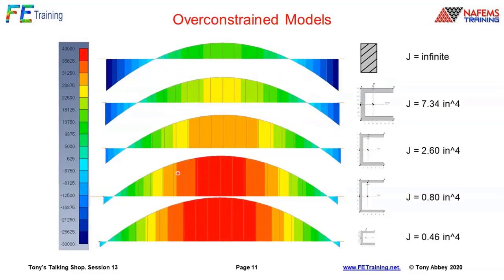And I've had great fun going through a range of different cases. I just use beam elements, it's very easy to set up. This is the guerrilla approach, which is saying that we're going to build in at that end and build in at that end. This is the bending moment diagram, and it's showing we go from like minus 30,000 root bending moment here, the root bending moment being the maximum bending moment, and then we're getting something a little bit less than that, so about 20,000 in the middle there. That, due to the distributed load, is the bending moment, and the bending stresses follow. So the critical region here is going to be the roots, and maybe we get some relief in the middle.